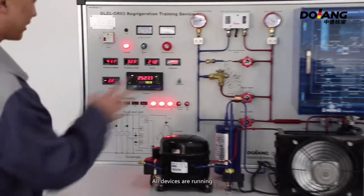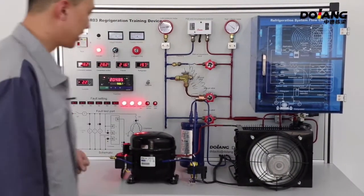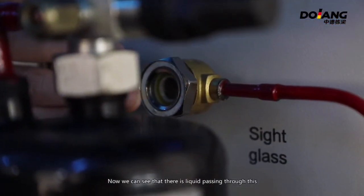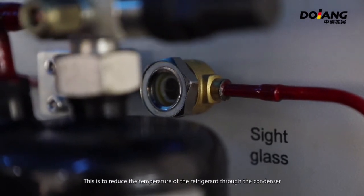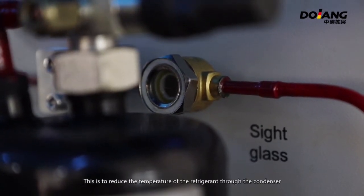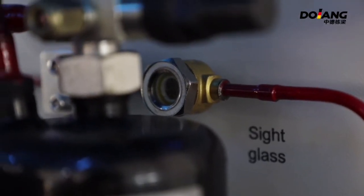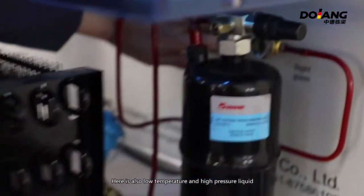All devices are running. Try not to touch the red pipe with your hands because it's hot. Now we can see that there is a liquid passing through this. This is to reduce the temperature of the refrigerant through the condenser. Here is also low temperature and high pressure liquid.